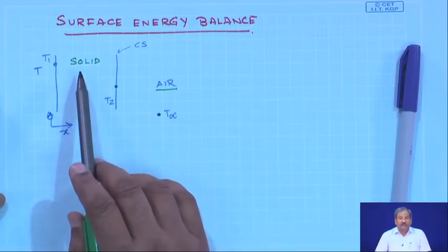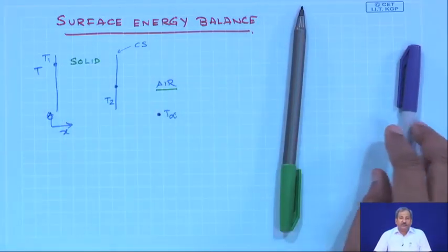So, in the solid, the principal mode of heat transfer, since there cannot be any motion of the molecules. So, in a solid, the heat gets transferred from one point to the other by means of conduction only, okay, as the molecules cannot, on an average, move from their positions. So, in absence of any heat generation in a system, and we will see why subsequently, in absence of heat generation and at steady state, the temperature distribution is going to be linear.